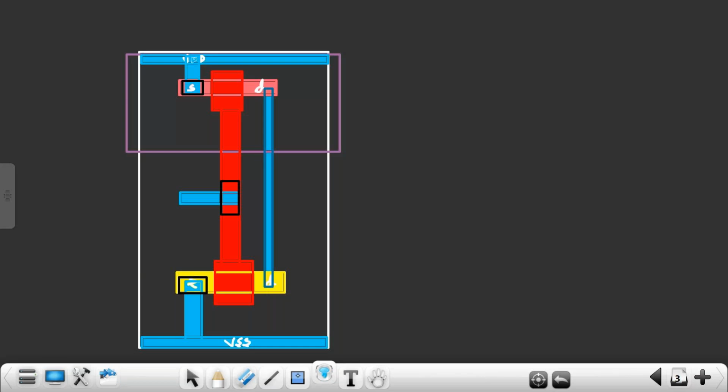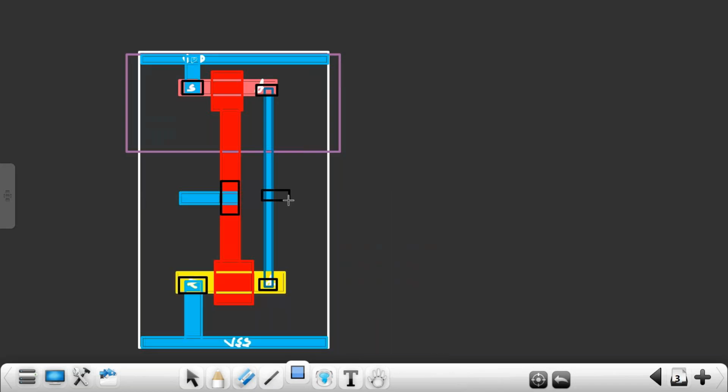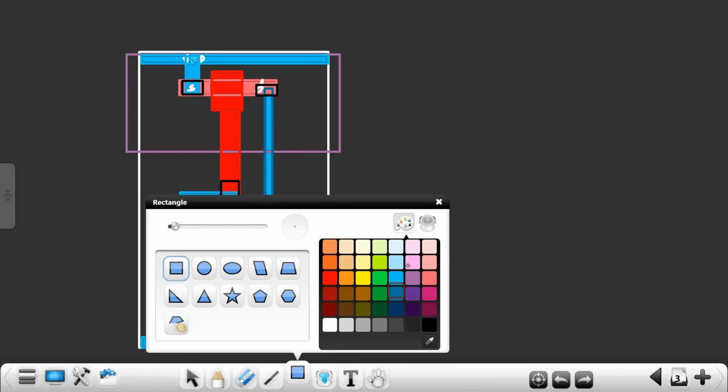By using metal layer. Again, I need one contact cut here, right? Because this is a semiconductor and this is metal. One contact cut here, one contact cut here, and here I will give one connection for output that can connect to the next cell.